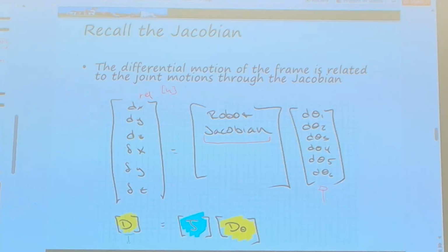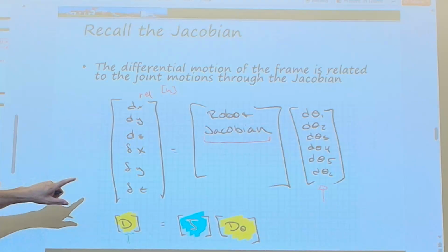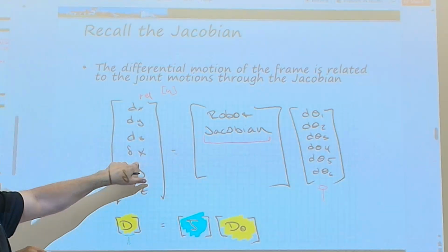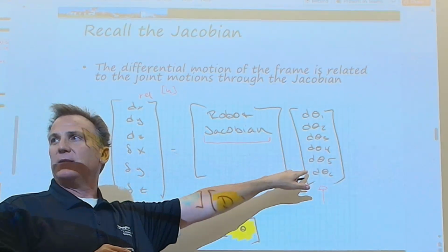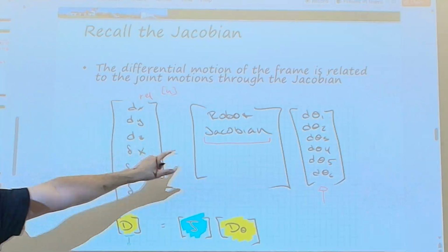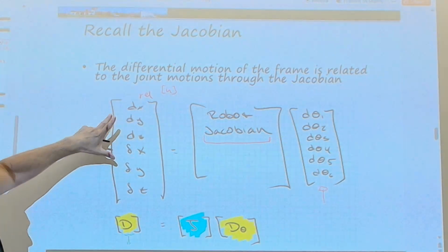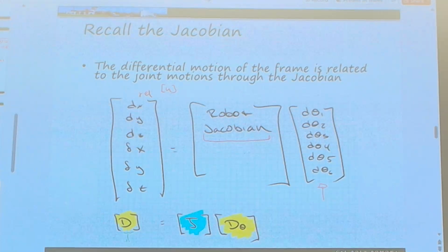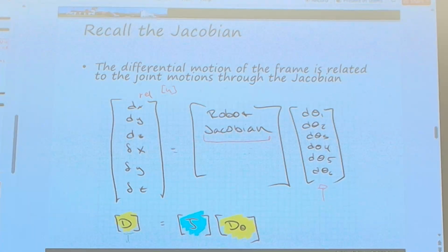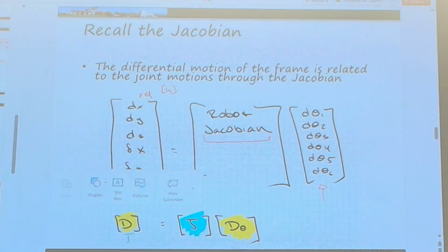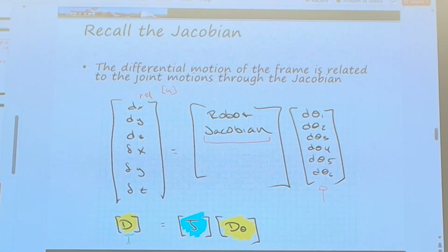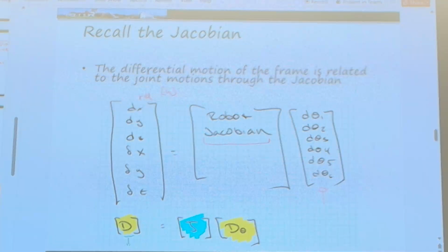So if position is driven by velocities, we're minimizing positional error in real space. So the position that we're really wanting is that position. Right. That we drive backward to this position. By velocity. This is the position we're interested in. Got it. Not these statements. But this position, if I control this position in my controller, that's going to drive these velocities. Because the relationships aren't proportional. Exactly. Because there's individual contributions from each one of those theta dots, resulting in dx, dy, dz, about x, about y, about z. So mathematically, it still would be in those positions if we were to drive those minimal changes, but wouldn't be there in real space.